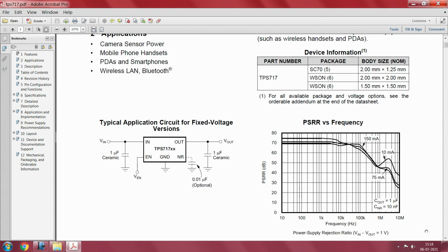It is not just here, this result is beautifully written for different load currents, as I mentioned. The influence of PSRR on the load current is one part, also the frequency component, the change in the frequency. It is giving you some flat structure for different currents. The one that is giving you the best must surely be for the lowest current.